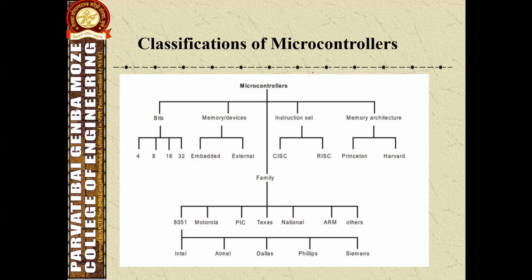The on-chip ROM is a flash ROM which supports an on-chip loader, so the program can be loaded into the on-chip flash ROM with the help of the serial COM port and an IBM PC. The in-system program loading of the DS89C4x0 through the serial port makes it ideal as a home development system.